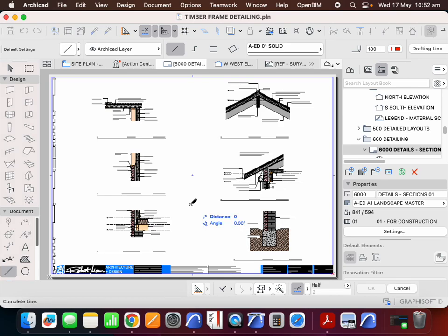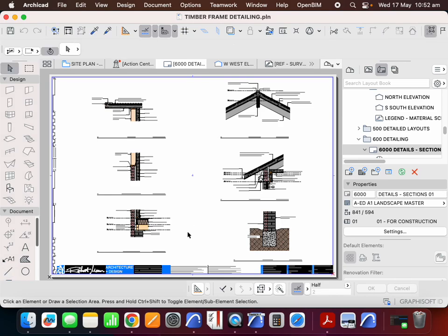I want to show you some timber framing detailing, because when we're doing a brick veneer or a timber frame and clad, it's all starting with the basic same premise. And I'm going to do this in a two-dimensional way because we're just talking about timber structural or timber detailing understanding. We're not getting into the 3D or the BIM components of how we actually create this with something like AutoCAD or Revit. So in terms of the 2D detailing, I tend to not use 1 to 20 in terms of full wall sections because you're repeating a lot of information that's really unnecessary.